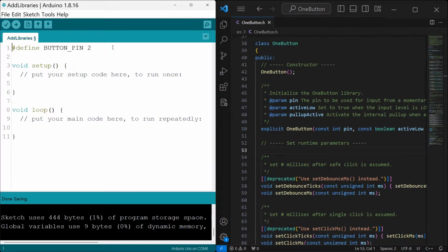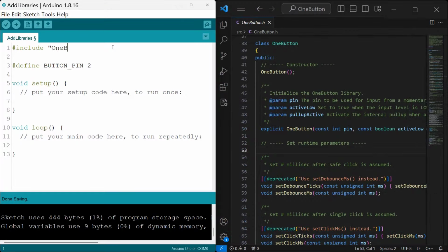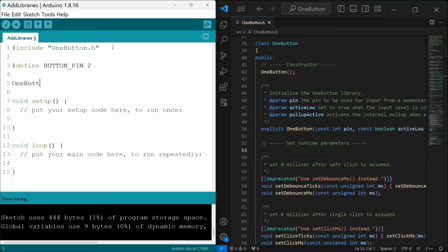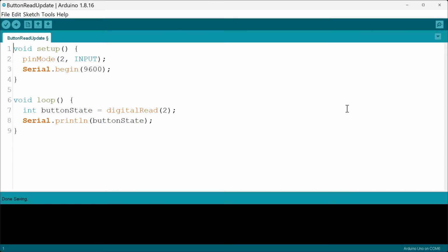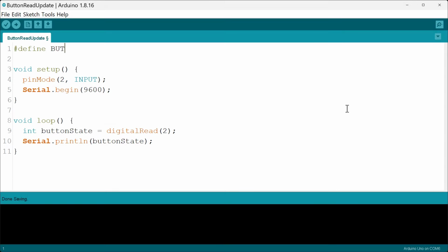We'll be including headers from other libraries later to offer us additional functionality so that we don't have to write it ourselves. I prefer hash defines for my pin numbers because I know they're not going to change during runtime, and the all caps makes them stand out.